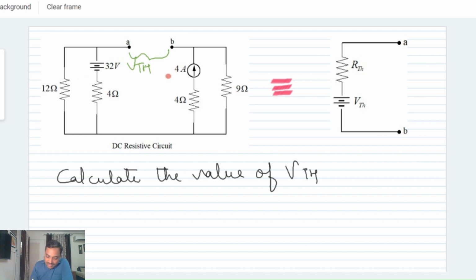network. I am using the mesh analysis method to determine the current flowing through each resistor, and while applying the mesh analysis, I can see that there are two meshes in this circuit. As for the third one, these are the open terminals and no current can pass through these 2 points.